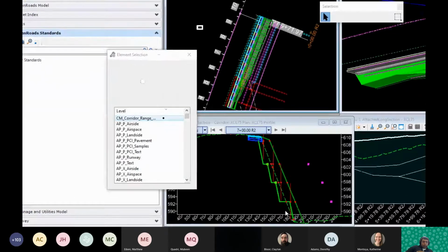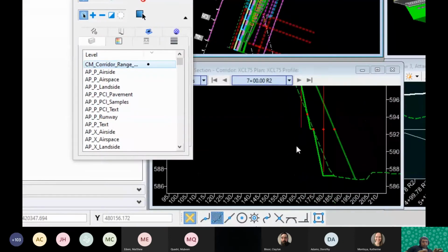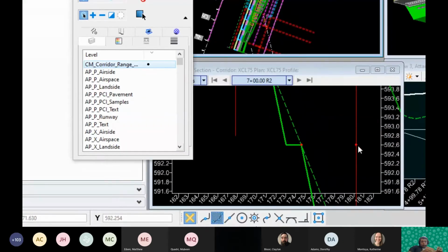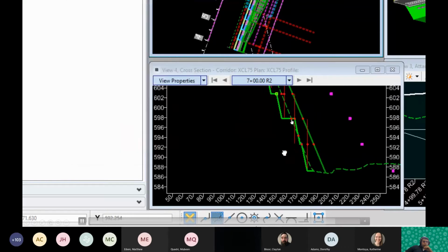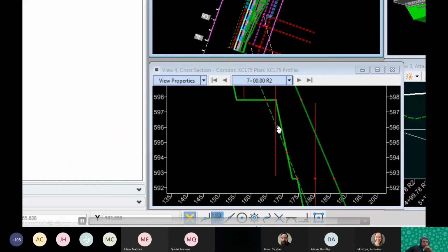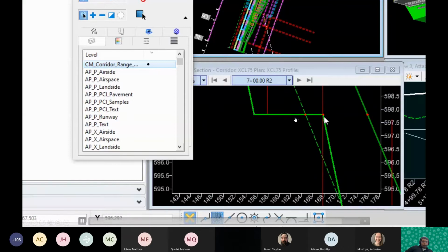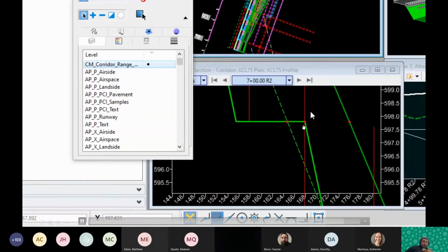So when I do that and I hit OK, granted this is just test data, so you probably wouldn't have a bench that small. But you see in this case, instead of going to the checkpoint, it said, "Oh, I can't go to the checkpoint. I have to go to the ground." And then if I look up at the one bench above it, I didn't do that. I just said go tie to my checkpoint, and so it tied directly to my checkpoint.